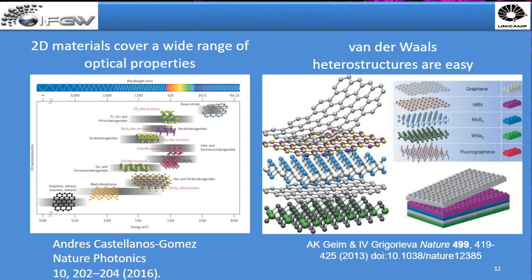So that's why many groups are investing a lot in studying heterostructures that are composed of tungsten selenide, molybdenum disulfide, or hexagonal boron nitride, and graphene, because you can think about conducting layers to make the contact. You can think about some isolating layers to have your device function the way you want it to function. And you can just stack this and it's supposed to work, right?